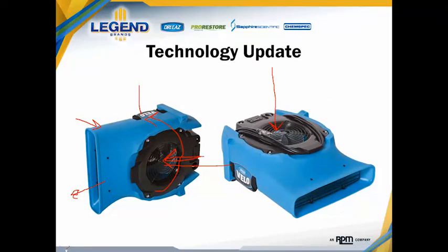And you'll notice when you take a look at this image that the snout or the outlet of this air mover has a downward slope to it, and the side of the air mover has an inward slope to it. These two effects are what we call stabilizers, a horizontal and a vertical stabilizer. And what they do is they ensure that all of the air generated on the inside of this air mover, if you'll notice by the shape here, is being harnessed and directed into direct contact with the flooring surface, which means more of the air ends up generating work in the drying effort.